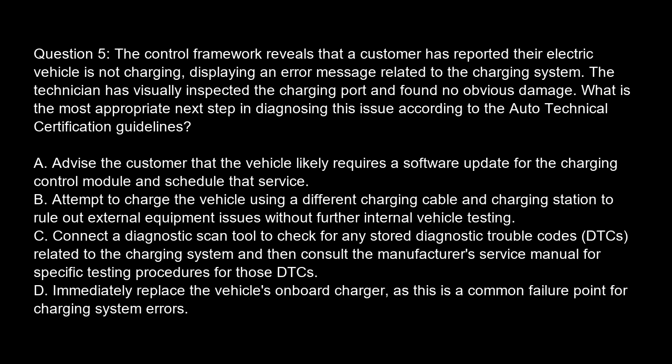Option C. Connect a diagnostic scan tool to check for any stored diagnostic trouble codes, DTC, related to the charging system, and then consult the manufacturer's service manual for specific testing procedures for those DTCs. Option D. Immediately replace the vehicle's onboard charger, as this is a common failure point for charging system errors.